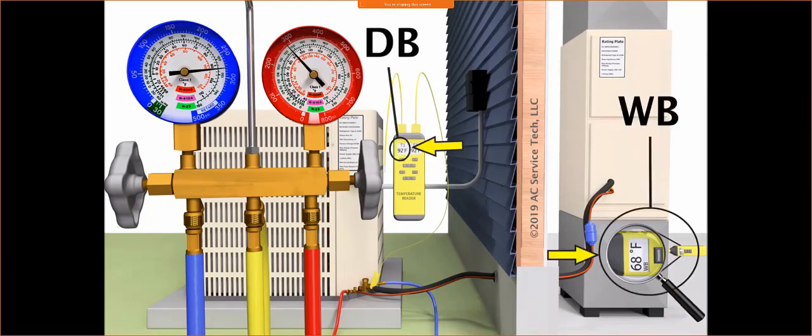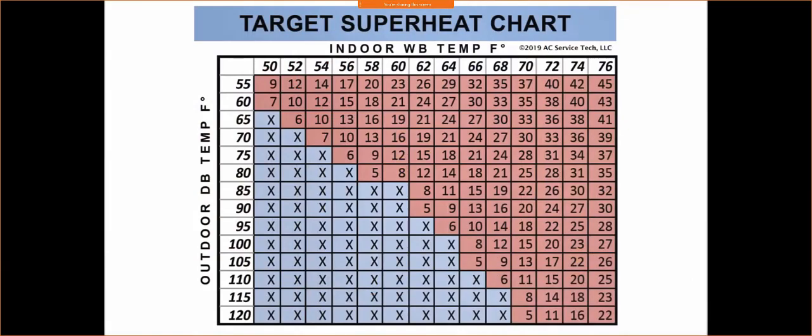You take that wet bulb and dry bulb temperature, and you can input that onto a target superheat chart, or you can put it onto a calculation or an app, and you could also just... I'm just going to pause it right there really quick.